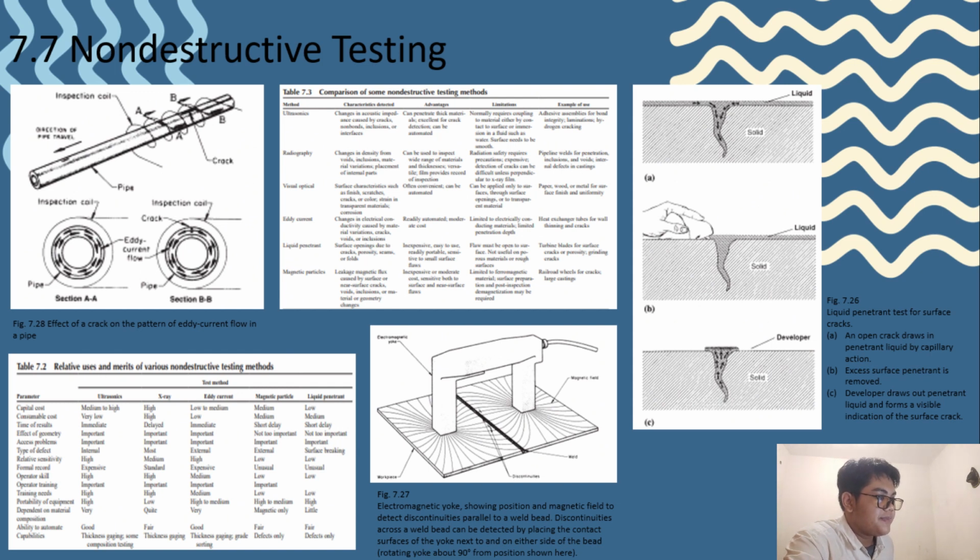Magnetic particle inspection is used to locate surface and subsurface discontinuities in ferromagnetic materials. The method is based on the fact that when a material or part being tested is magnetized, discontinuities that lie in a direction generally transverse to the direction of the magnetic field cause a leakage field to form at and above the surface of the part. The presence of the leakage field, and therefore the presence of the discontinuity, is detected by magnetic particles applied over the surface.